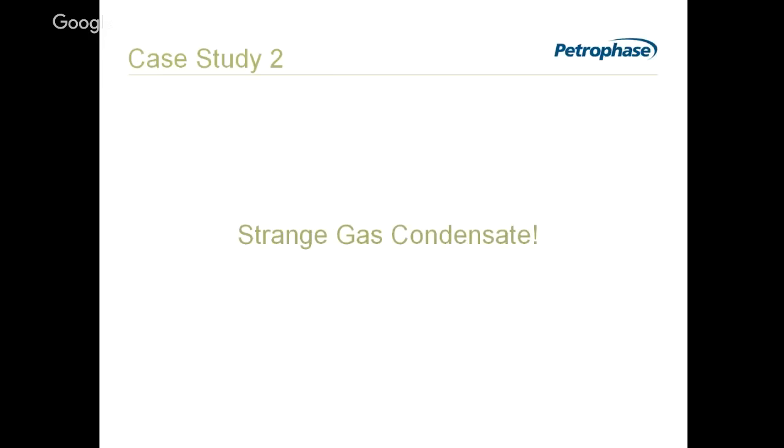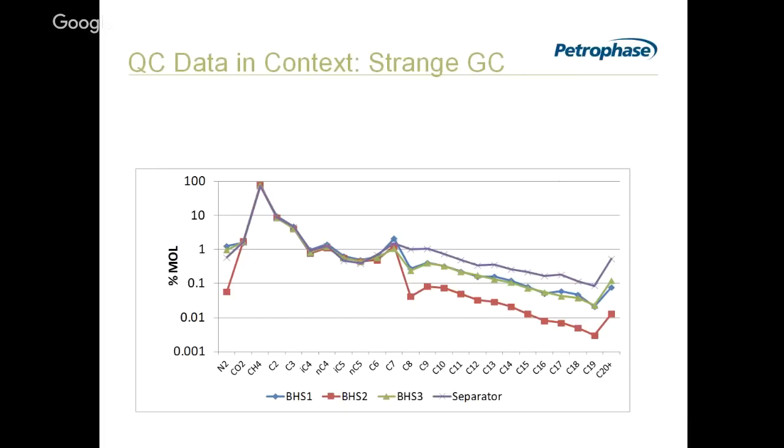We've done our PVT, we've done our constant composition, constant expansion, CVD, the mass balance of the CVD came out really good. But the fluids that we get, we can't match that against the well test rates. It makes no sense. And again, samples were taken at surface, samples were taken downhole. If we compare the compositions here, there's a wide spread. Two of them, the blue and the green points, overlap.